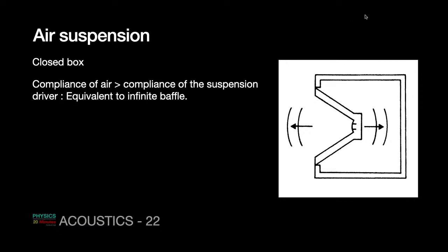So if it's a large air volume, then the air tends to become very soft. The compliance is much higher, and therefore most of the back wave is absorbed completely, and that design is equivalent to an infinite baffle. Remember, this is when the box is much larger than the speaker.